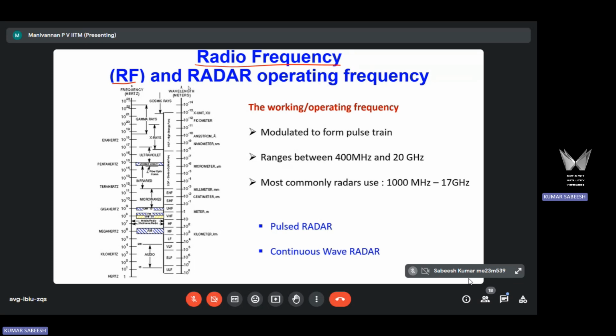Right? That's one thing. So you can see that the frequency of radio waves starts from 1 hertz. 1 hertz means, for example, we think of a sinusoidal wave. It takes one positive and negative cycle. This is one cycle, right? The total duration is 1 second. Positive half cycle, 0 seconds. This is t equals 0. It starts from 0, increases positive, and this one again 0 gives the 1 cycle. This is 0.5 seconds. This is 1 second. Then the period, capital T, equals 1 second, correct? What is f? f equals 1 by T. 1 by 1 is nothing but 1 hertz, right?